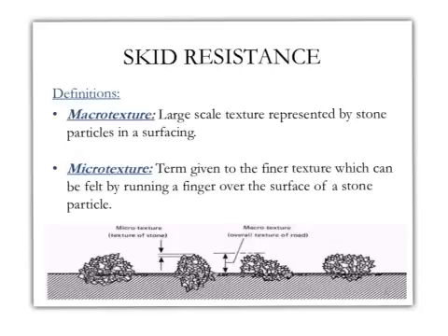If you take a look, for example, at this aggregate piece, half of it is stuck in the asphalt and the other half is outside, on the surface. So the macro texture is the entire overall texture of the road, which is the total distance from the surface of the road all the way to the height of the aggregate piece.